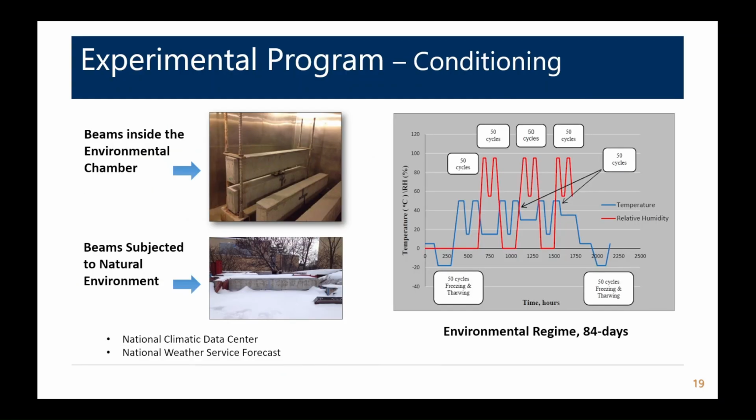In terms of the environmental conditioning, this is an 84-day exposure condition, and what we try to accomplish is looking at different temperatures, different relative humidities, as well as stress and no stress. You can see in the upper left figure the spring system that we use to apply sustained loads on the members in the environmental chamber, and then we have some outside.